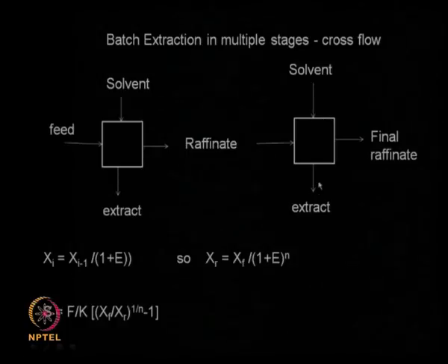All these extracts from each of the stages will be combined together, and that particular extract will be very rich in your solute. This is called a cross flow, because your feed is flowing like this, and your solvent is coming crosswise from the top.